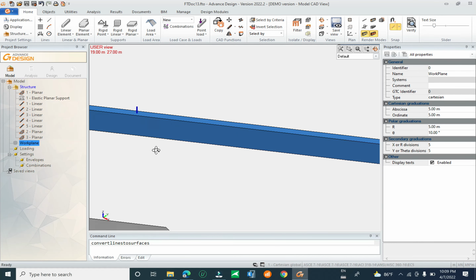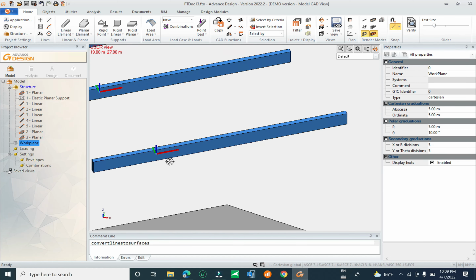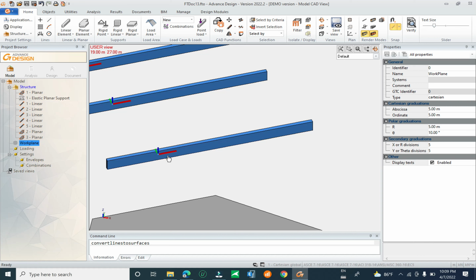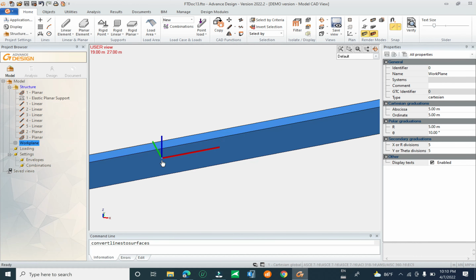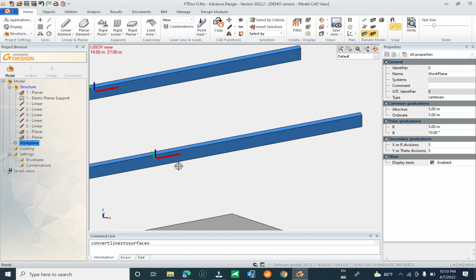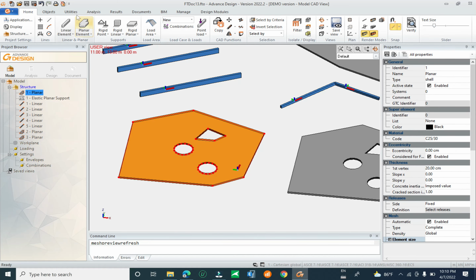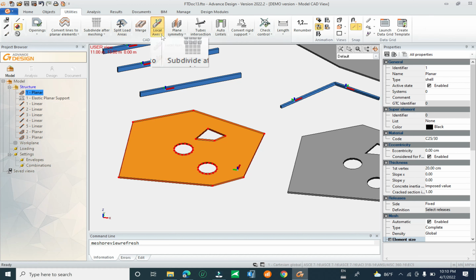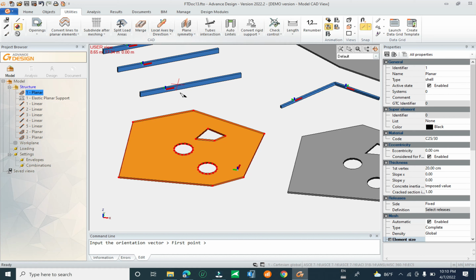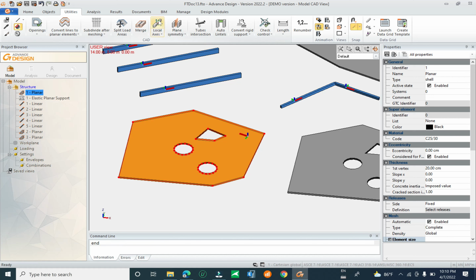And for the beam element, the along element is x axis, and this one is y axis, and the upward direction is z axis. Now you can change. You can select this object, and after that you come back to entity and core axis by direction. You can change. Again core axis. Okay, you can change the core axis and click it.